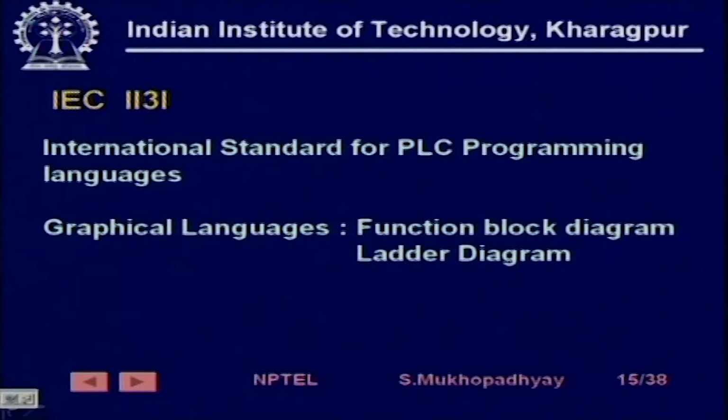One are graphical languages, things like functional block diagrams or ladder diagrams. On the other hand, there are several text based languages, for example, structured text or instruction list. These are some of the kinds of programming paradigms. I already told that although we are learning about the RLL, there are several other programming paradigms which are also supported by various manufacturers, and these are typical examples of them.